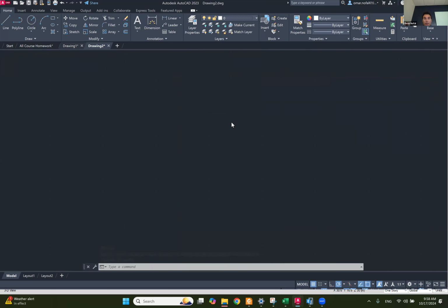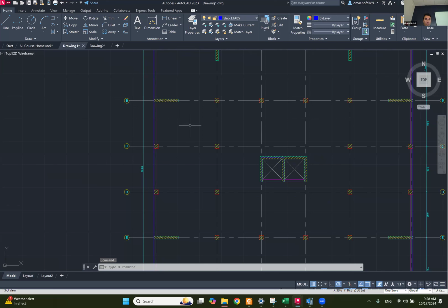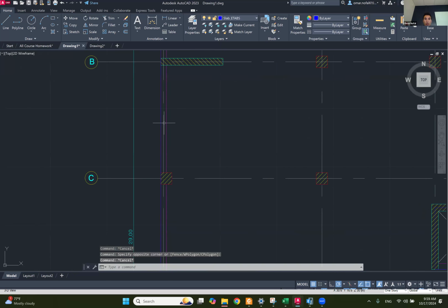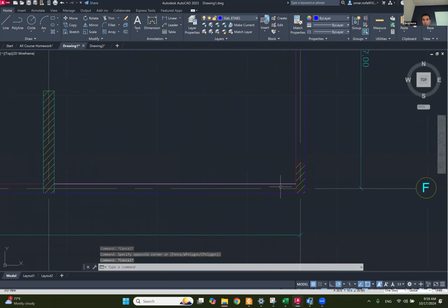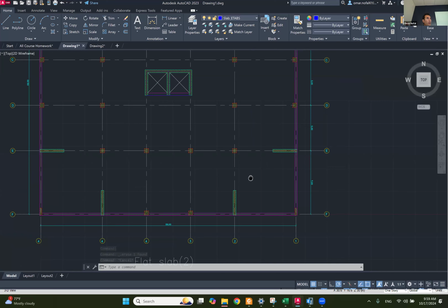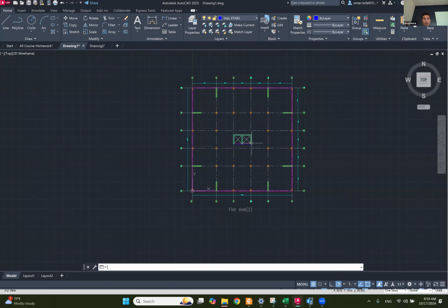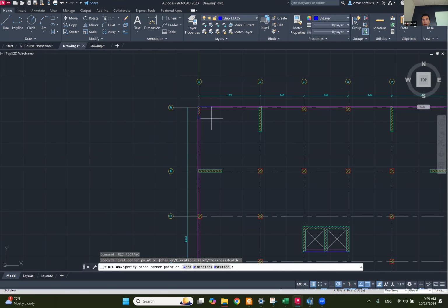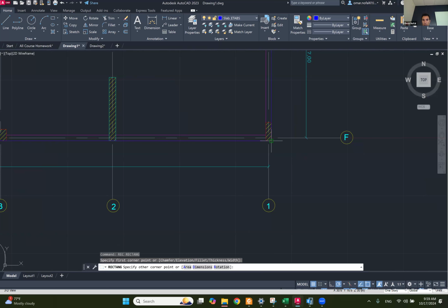I have a similar drawing here. And I make sure I already drew the slab in this blue line as a rectangle area. Like when I click on it, this one, maybe I can delete it and draw it again. Okay, so I have slab ETABS here. The layer is activated. You all can use AutoCAD, right? Okay, so I'm going to make a rectangle, and I'm going to start my slab from this corner and end at this corner.